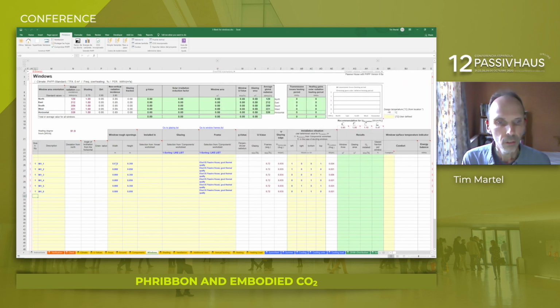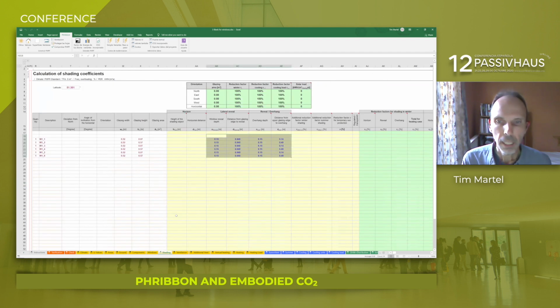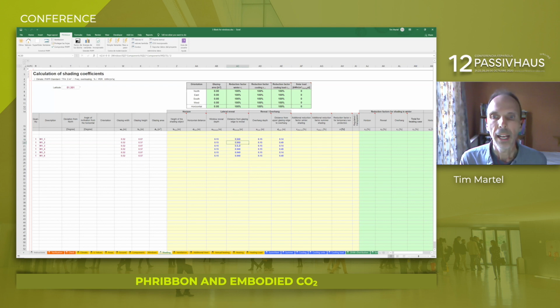And it writes the window sizes there, the dimensions of each pane, the frame information, the 1s and 0s, but much better than that is that it calculates the D-reveal. D-reveal is quite complicated to calculate yourself, and it puts it in as a formula which allows you to see exactly where the information came from. It also calculates the D over, which is not so straightforward. It takes information from the frame size and also the size of the window above it.